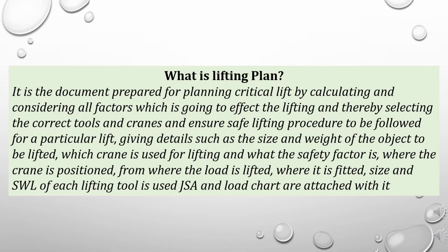What is a lifting plan? It is the document prepared for planning a critical lift by calculating and considering all factors which affect the lifting, and thereby selecting the correct tools and cranes and ensuring the safe lifting procedure to be followed for a particular lift, giving details such as the size and weight of the object to be lifted, which crane is used for lifting, what the safety factor is, where the crane is positioned, from where the load is lifted, where it is fitted, and size and SWL of each lifting tool used. JSA and load chart are attached with it.